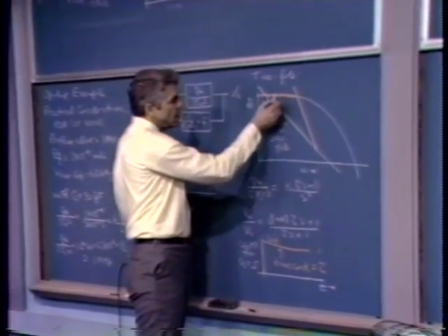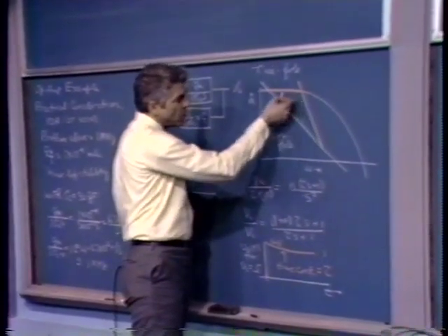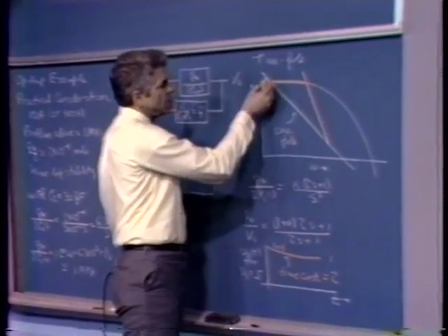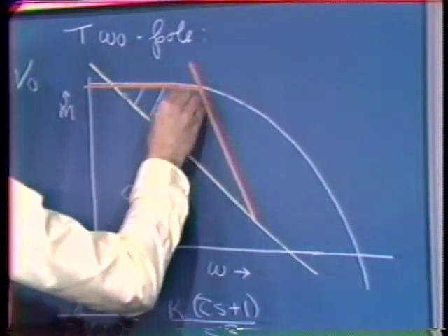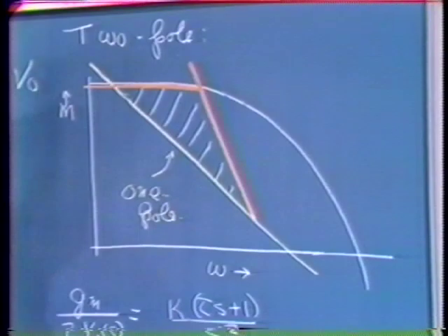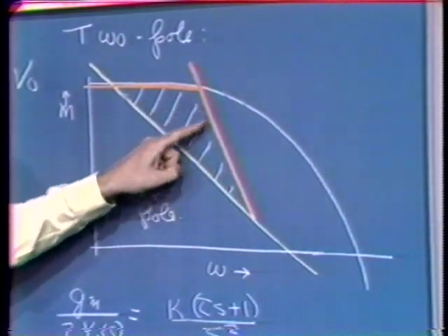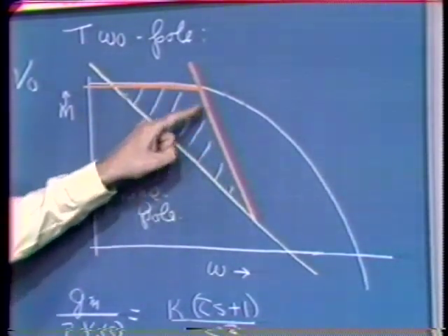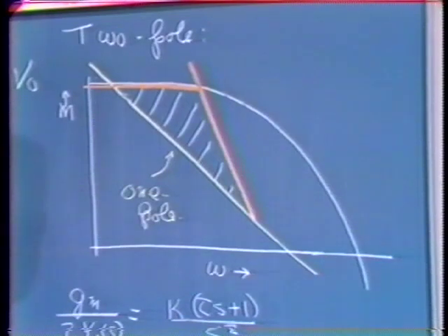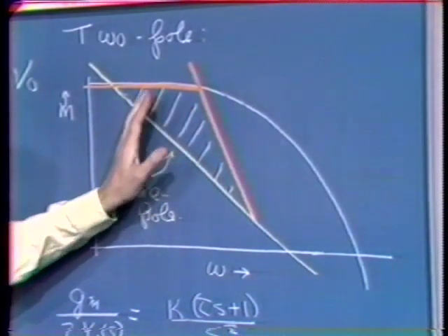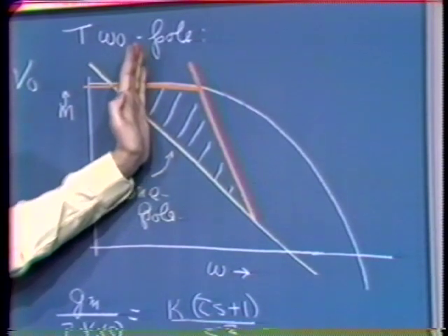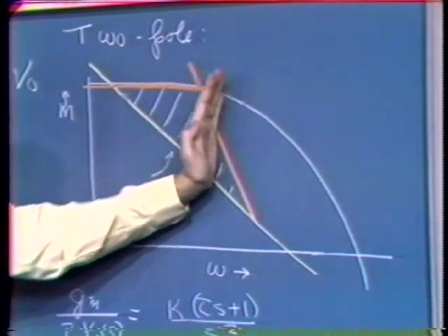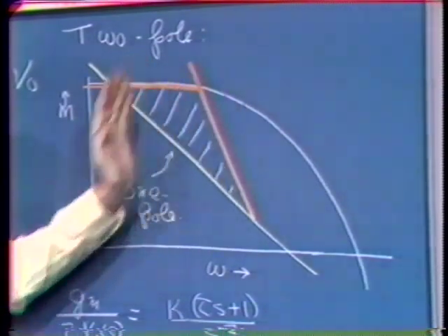We have the orange curve showing the 1 over S squared compensation, the yellow curve showing the single pole compensation. And over all of these frequencies, we have considerably higher open loop gain from the two-pole compensated amplifier. We'd anticipate improved desensitivity for any signal where the majority of the signal frequency components lay in this region, where most of the signal energy was concentrated.